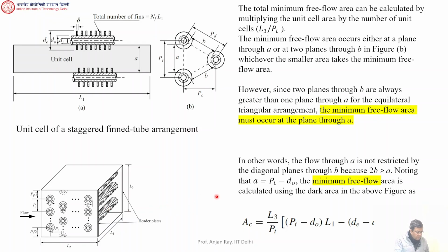So that will depend on this sort of area, which is AT, including the tubes and the fins, divided by this dimension. What is this dimension? L2. So we are constructing something like a perimeter by calculating AT over L2.